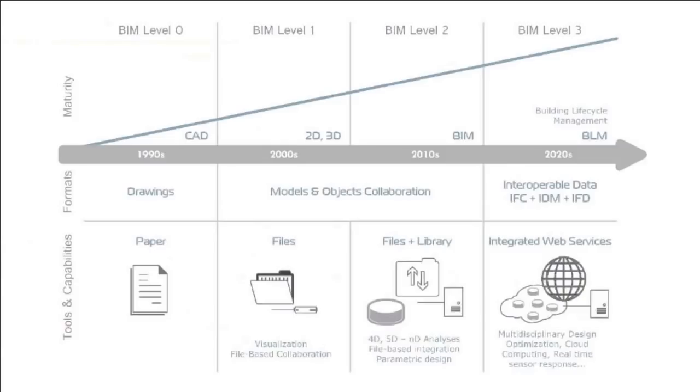You can assign a specific symbol a specific plant definition that carries through, and you're able to document everything that's tied to that definition. Similarly, irrigation heads have catalog information. So all of the information that's associated with, in my example, a Hunter I-20, down to its pressure loss specs, is attached to those irrigation components.